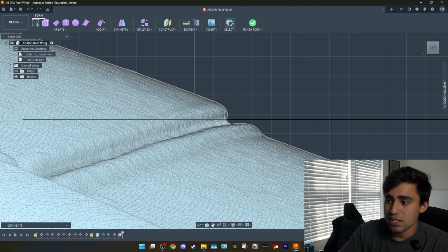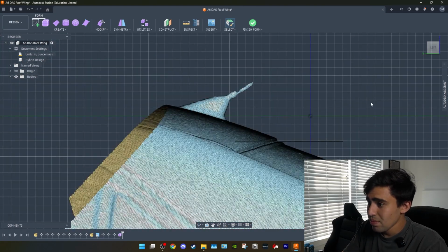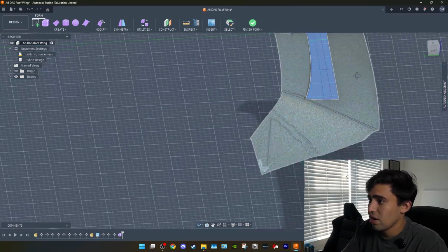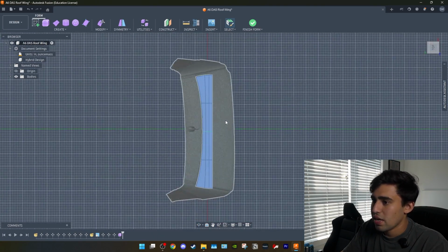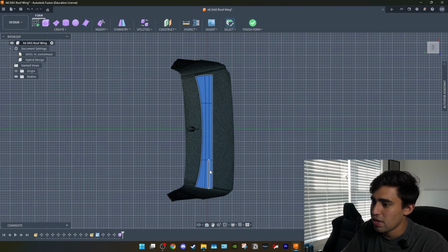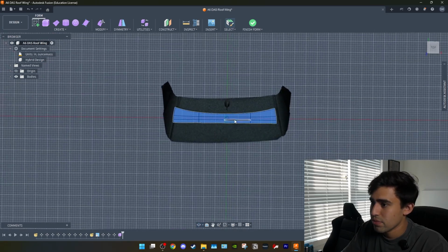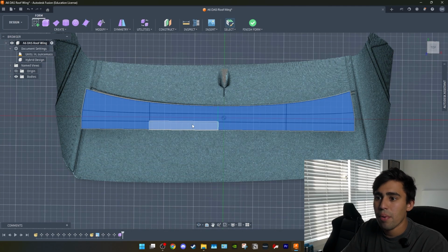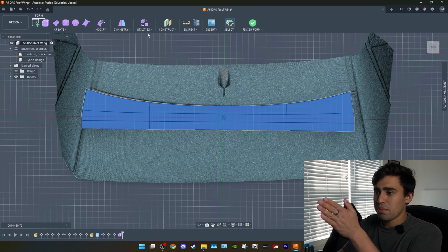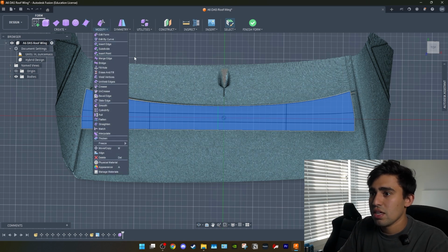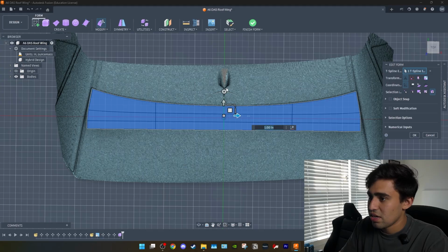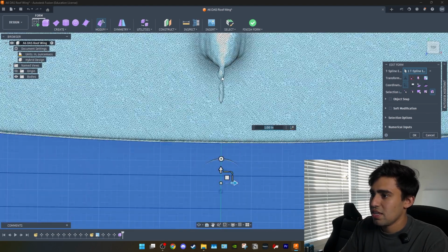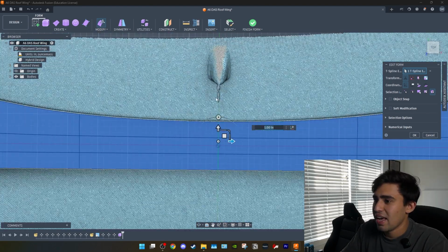or the scan itself. And I'm going to harp on this multiple times throughout the video. I'm learning the same time you're learning. So if you look at the top, it fits the curve of the entire thing very nicely. But I just realized something. We accidentally moved it towards the left. So simple fix, edit form, entire body, and then you could just move it back to center, which is right here. I'm using this stupid looking antenna as the center.